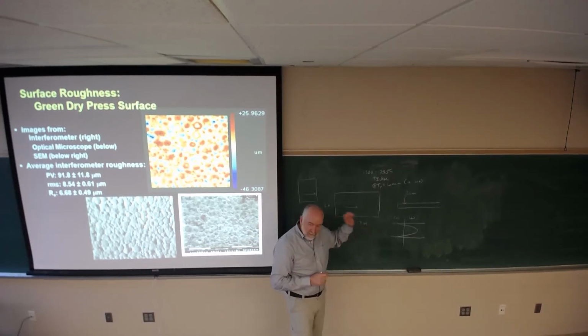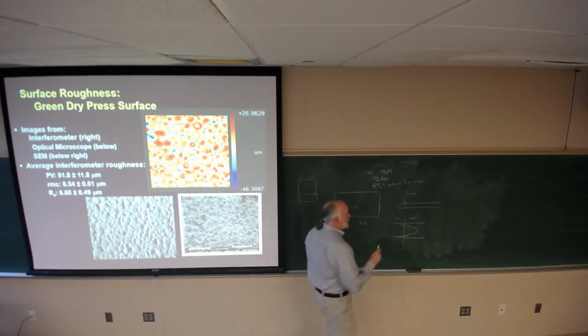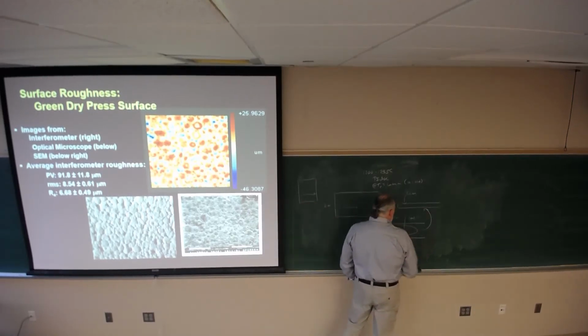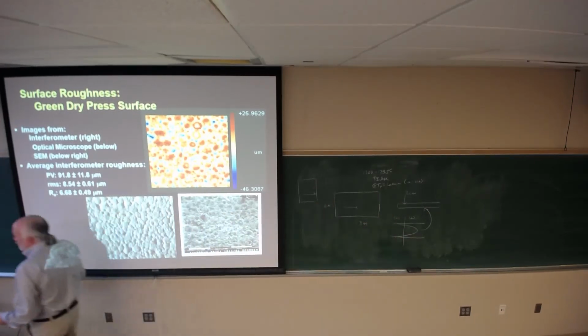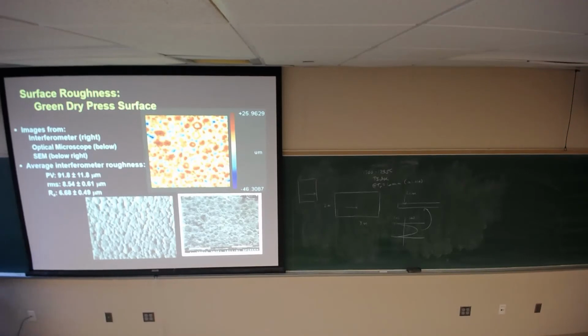You think that because of the rapid cooling that occurs in firing tile, we have the same situation in tile, which is really fascinating. And you say, well, what's the deal? The deal is that you have a thermal expansion coefficient for the tile, which we're going to talk about later, a finite thermal expansion coefficient, and you're cooling that system extremely quickly. And when you cool that system quickly, you place the surface in compression.